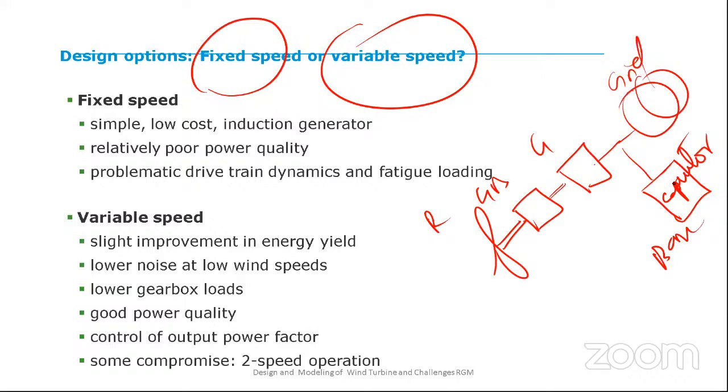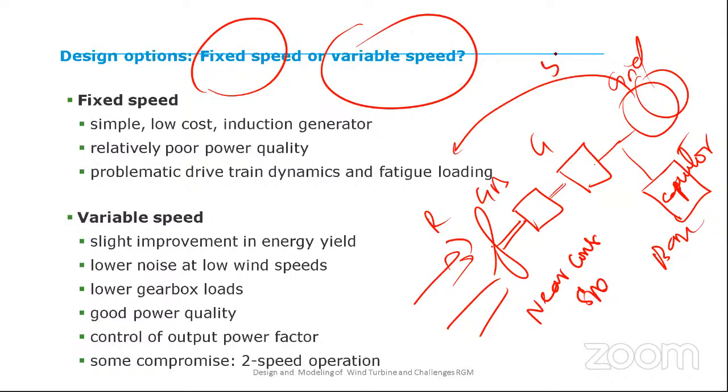The fixed speed turbine, irrespective of the wind speed, always rotates at a constant speed. Exactly, not near constant speed. This speed is fixed by the grid frequency. Our grid frequency is 50 hertz. It will not allow more speed because it is controlled by the grid.